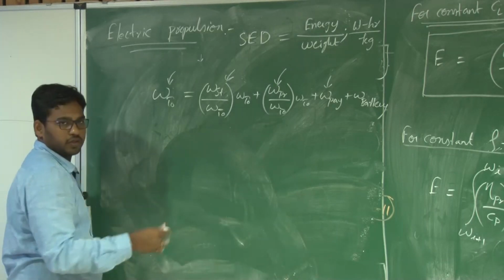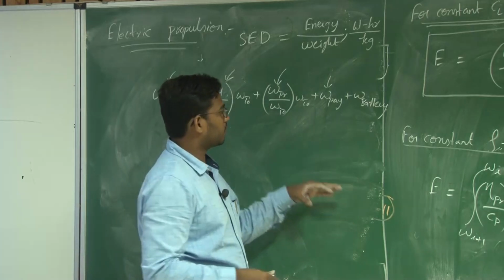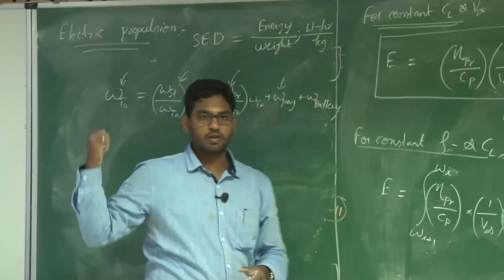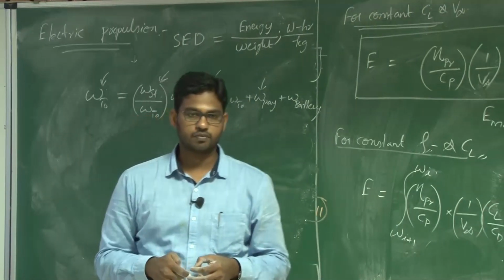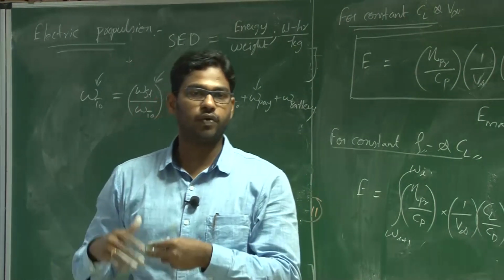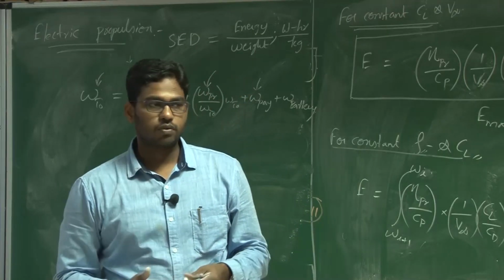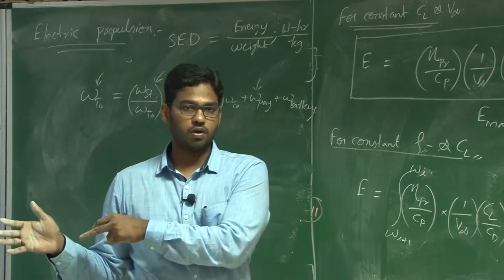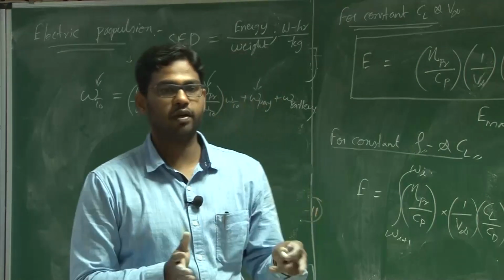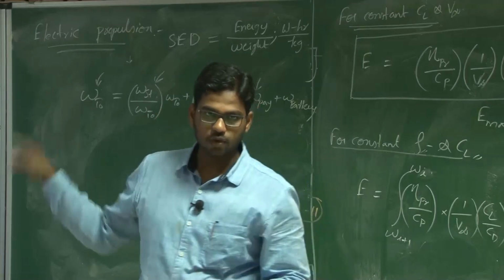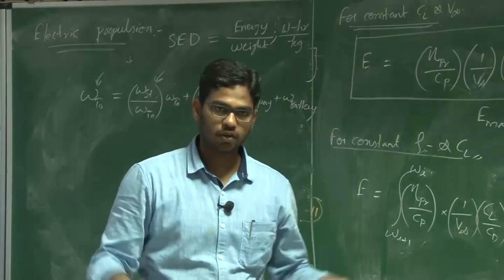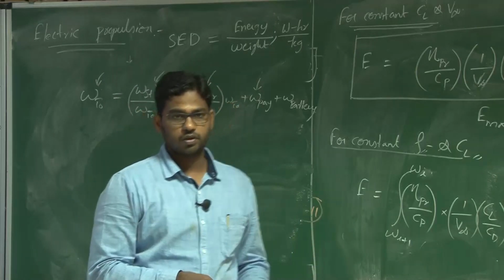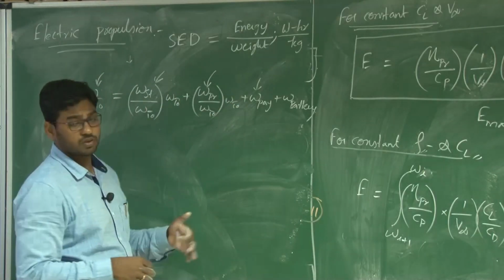So it's an iterative process, but in this we will try to address, if this is the overall takeoff weight, what is the percentage of battery weight for that overall takeoff weight. Let us say if you want to build a UAV of 5 kg, you should know what fraction of this overall weight of 5 kg should be the battery weight, right? So let us solve that problem first, and then we will see how this iterative process works to actually find the weight estimation of the new design.